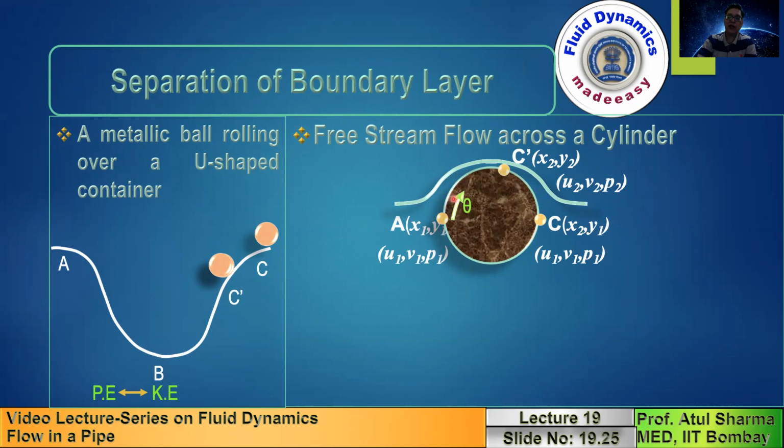and in this problem the circumference of the circle, you have a streamline, and this is another streamline, and between two streamlines the fluid cannot flow across the surface of the streamline. So when the fluid cannot flow across the surface of the streamline, whatever fluid is entering, you can see that this is like an internal flow situation between the two streamlines, and we know that the fluid cannot penetrate a streamline, so it has to pass through this cross-sectional area.